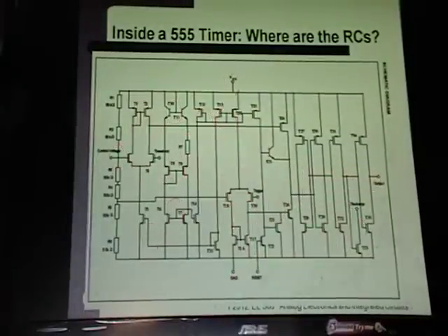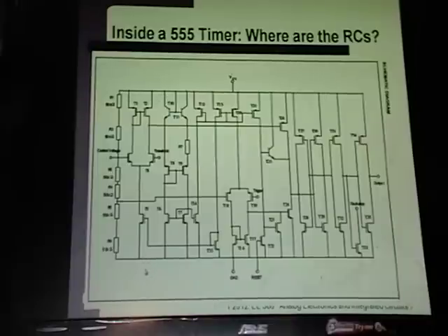That sounds really painful to me. So what you usually do is you look at your signal path. It's the signal path that's going to be affected. If there's capacitance on the supply or on ground, that's actually a good thing because it's going to quiet it. But along the signal path, so here's your VN, here's another VN, goes out here.